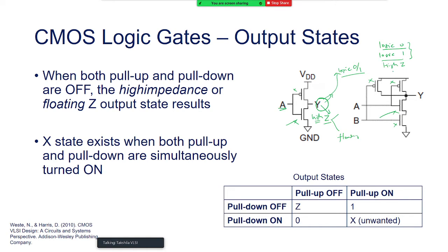Okay, so remember that there are two logic levels, but there is another logic level that is called high Z, and usually high Z can happen if the switching network is completely off. Every transistor in a switching network, in a CMOS, when we talk CMOS, remember it will always have PMOS and NMOS, and they are both off. So in that case, you go to the state called high Z.